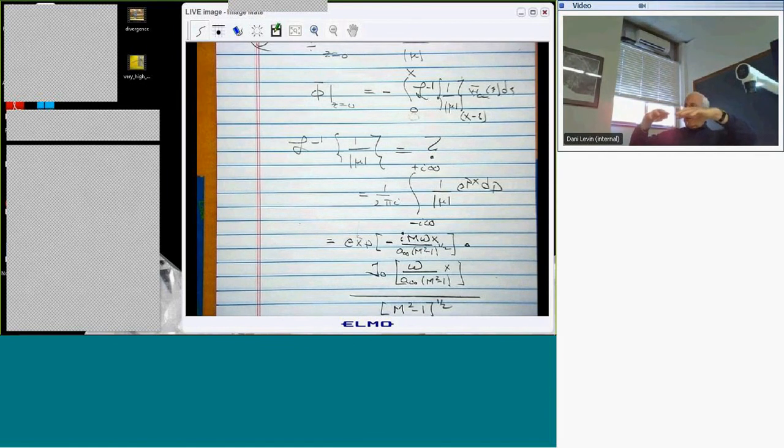You actually use it in the Navier-Stokes equations. And then in the far field, they use potential flow theory, because if you try to use the Navier-Stokes equations in the far field, it would take forever. Well, a graduate student could do that for the PhD thesis, but if you're working for Boeing and want the answer this week, or even this month, or maybe even this year, you wouldn't want to do it that way, right? But you can show that piston theory gives you the potential flow solution, which is also computationally tedious for large Z. And so that's been worked out too.